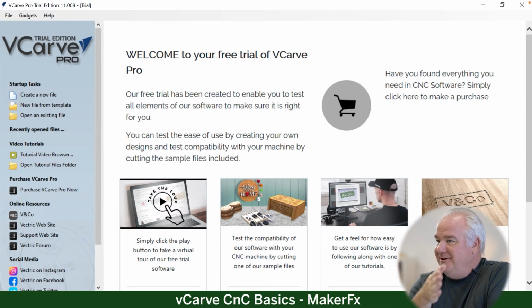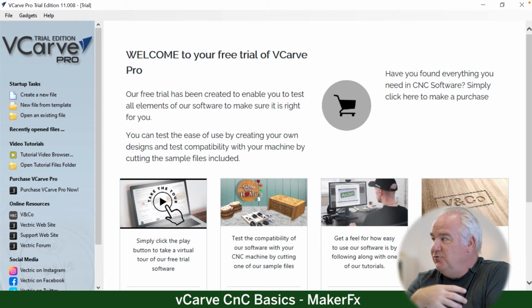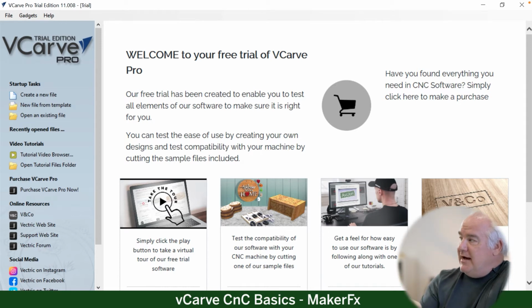Unfortunately, it's different software. So step one is VCarve Pro for design, and step two is also VCarve Pro for getting the design ready. We call that toolpathing. There's a variety of tool chains that can be done. Today we're going to talk about the most common and the simplest tool chain, but on the design step, you can do design work in other applications such as Illustrator, AutoCAD. I mean, anything that can create a vector file, you can do that design work. The toolpathing, that particular design software may not have the ability to do toolpathing, so you can't do toolpathing in Illustrator. But the most common pattern or steps are VCarve Pro for design, VCarve Pro for toolpathing, and VCarve Pro will create a file that has to get actually used to operate the CNC.